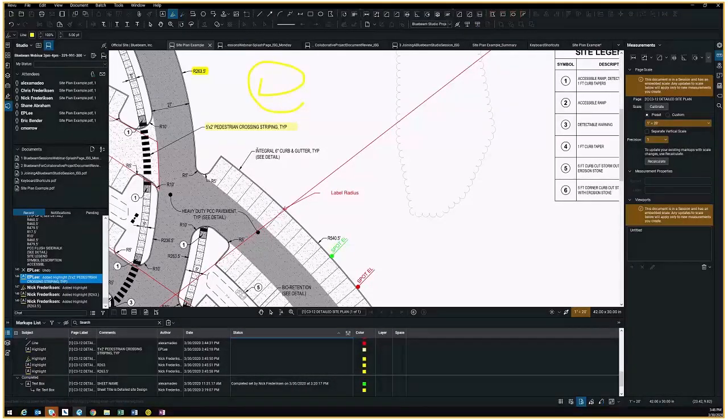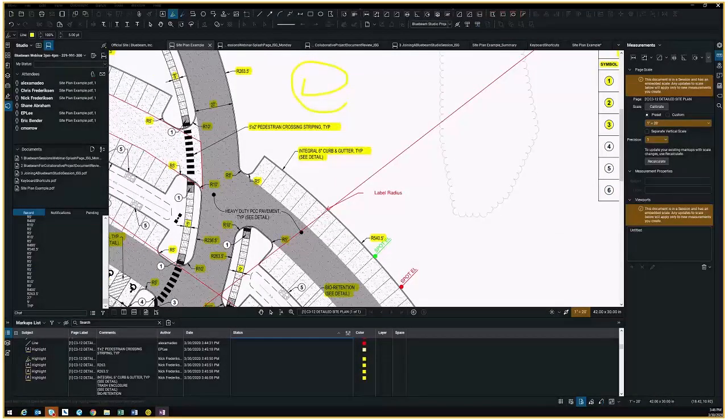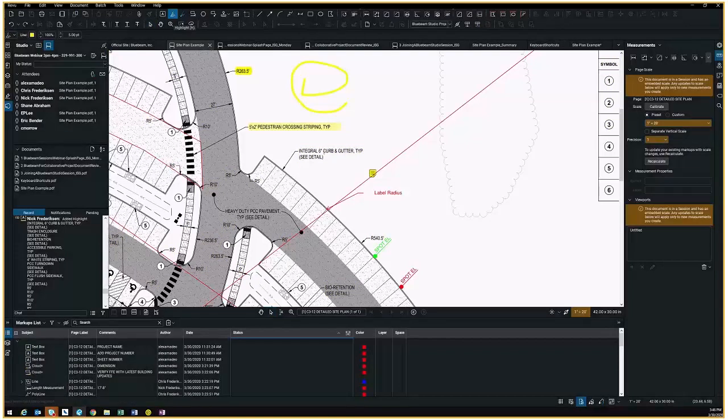If you are consistently getting text and you want to go freehand, you hold in the shift key. Now, let me undo that. I didn't mean to. As you're highlighting text, if you hold in the control key, it will allow you to go back to freehand over that area where it would not normally allow you to highlight text. So there's a number of tips and tricks that way.